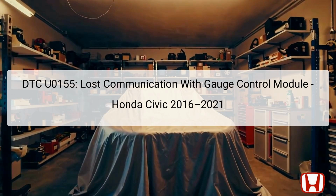The Diagnostic Trouble Code, DTC U0155, indicates a loss of communication with the gauge control module in Honda Civic models from 2016 to 2021. This code typically arises due to failures within the Controller Area Network, CAN, which is responsible for transmitting and receiving signals among various control modules, such as the Transmission Control Module, TCM, and Gauge Control Module. When proper communication ceases for a specified duration, or data sent from the Gauge Control Module is deemed abnormal, the TCM triggers this fault code.